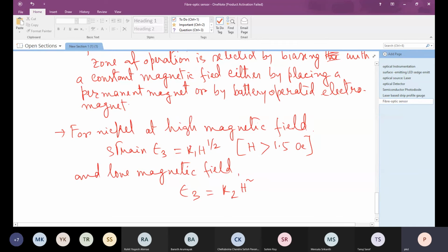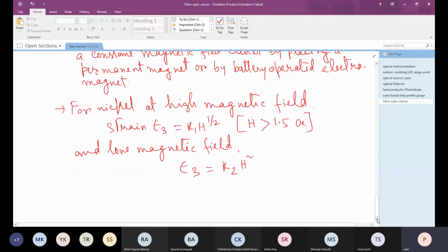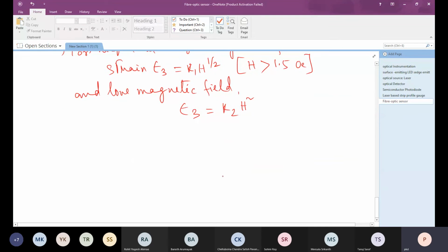Where basically when the magnetic field perturbation is of lower value, the variation is more in square terms, and it is saturating when the magnetic field is high. So the saturation is approximated by a square root here. A better approximation could be, say, exponentials, but for ease of calibration, manufacturers often use such a method.